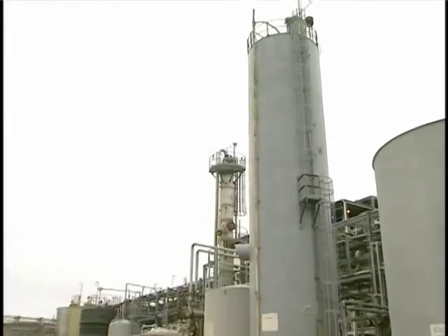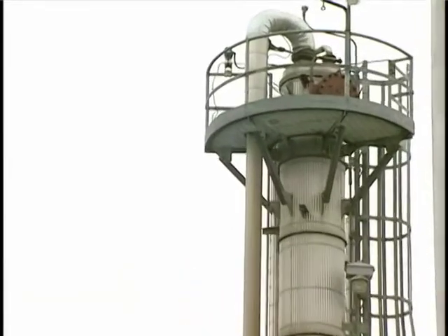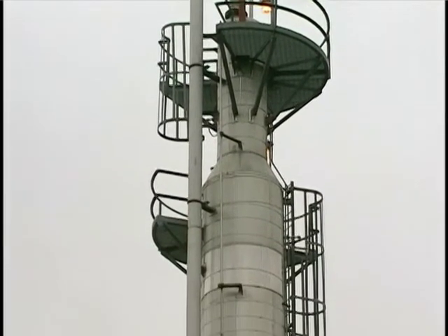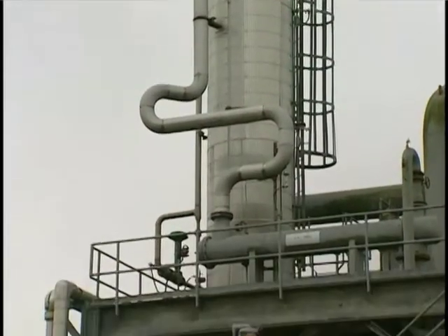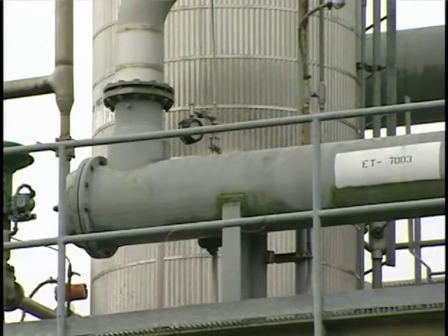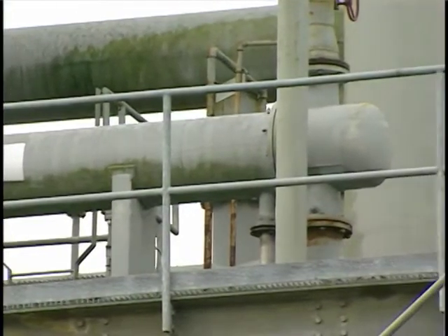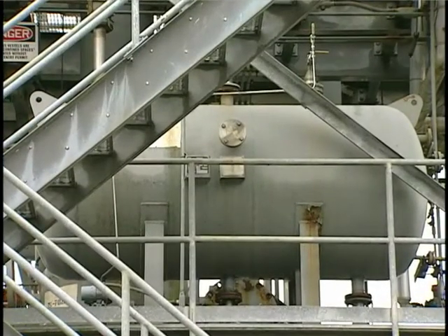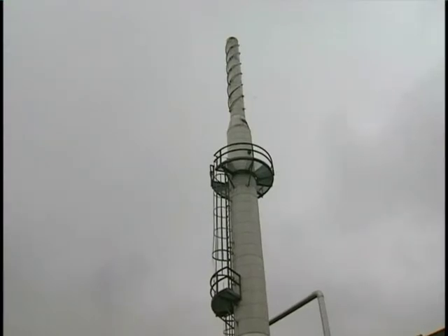One application of condensers is in the steam stripping of wastewater to remove organic compounds. The contaminated wastewater is directly contacted with steam in a countercurrent tray tower. The volatilized organics and any uncondensed steam are collected from the tower and condensed in a water-cooled shell and tube condenser. The recovered condensate is separated in a decanter to recover the organic compounds, which are either returned to the process or incinerated to recover their energy value. The non-condensable organics exiting the condenser are usually incinerated.